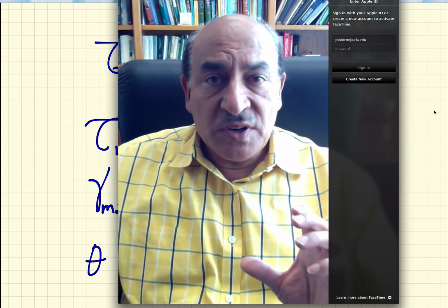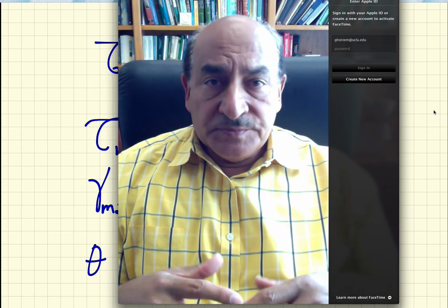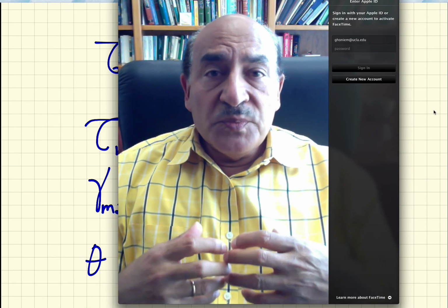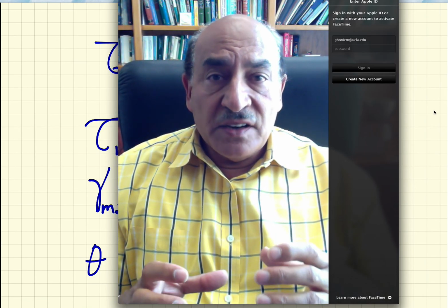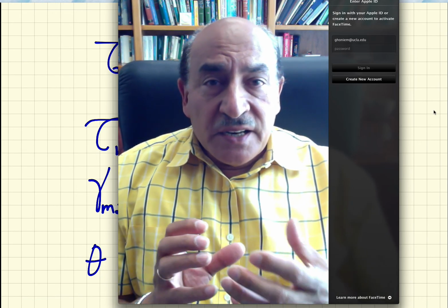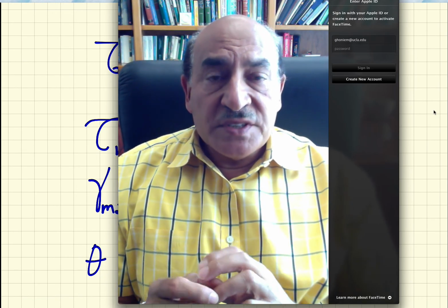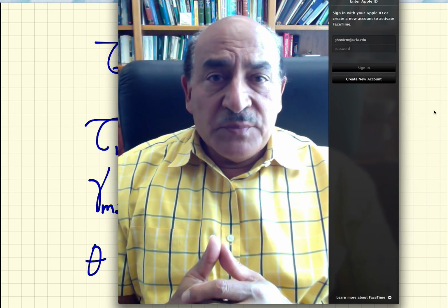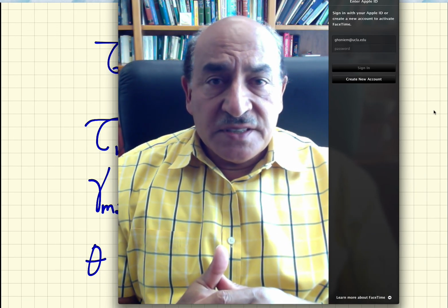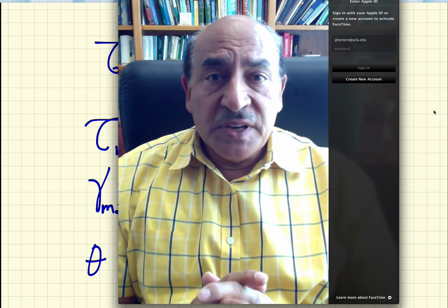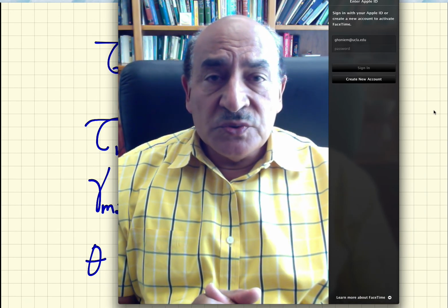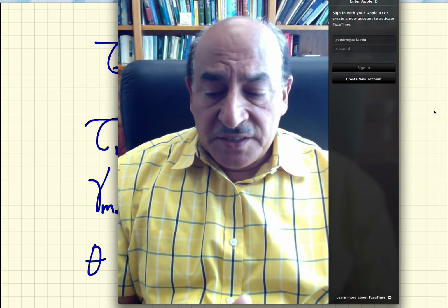So GJ, the product of G times J, we call the torsional rigidity, because if the cross section has a very large value of GJ, then it will be very rigid and we cannot twist it very easily. So this is kind of the main ideas, and let's now review that again here with a little bit clearer pictures, and then move on to non-circular cross sections.